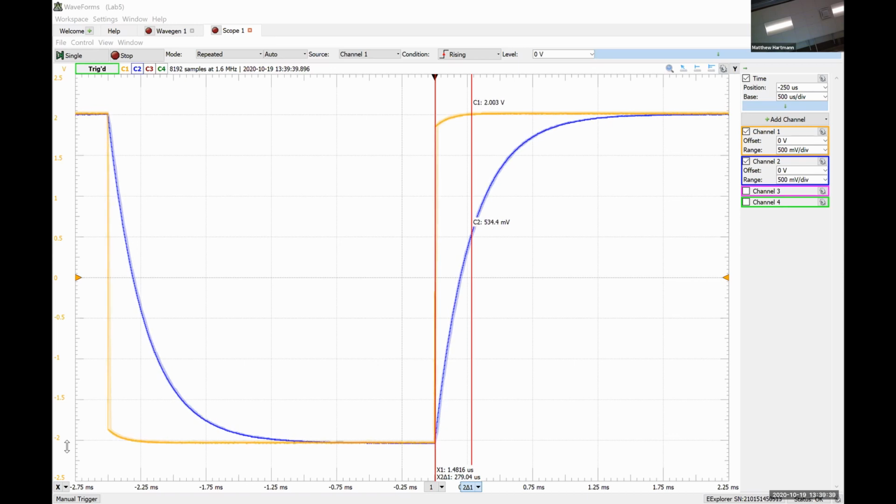If we further look at this sheet, it says the voltage across the capacitor, which is oscilloscope channel 2, the blue curve, should have an exponential form fitting the equation A e to the -t over tau plus B. Now, hopefully that equation form is pretty familiar to you all, because I just wrote it down a minute ago, effectively. But what does the term B represent in that equation in your lab sheet?